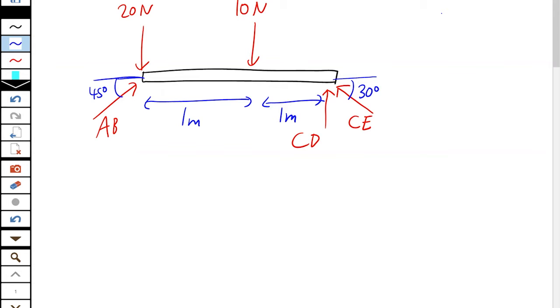And we don't know whether they're tension or compression. Here, they're all holding the thing up, so I guessed compression, that they're pushing. It doesn't really matter. As long as you draw a clear arrow, the math will come out and tell you it's either plus in the direction of that arrow or minus against the arrow. Now, before you start doing math, always draw your axes. This helps avoid embarrassing mistakes, and it makes it a correct diagram.